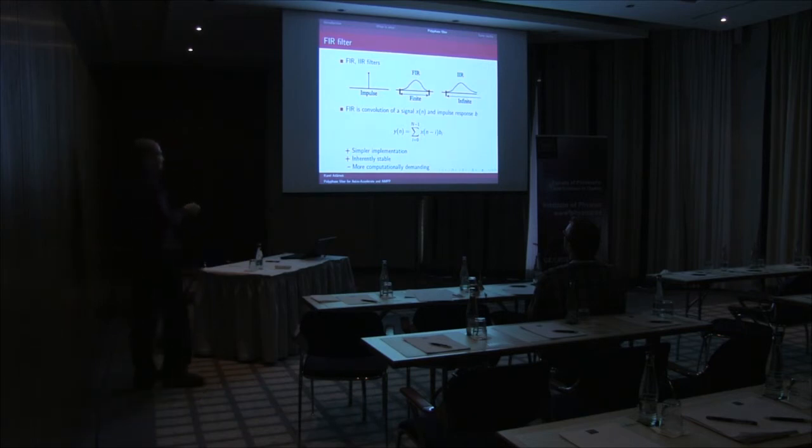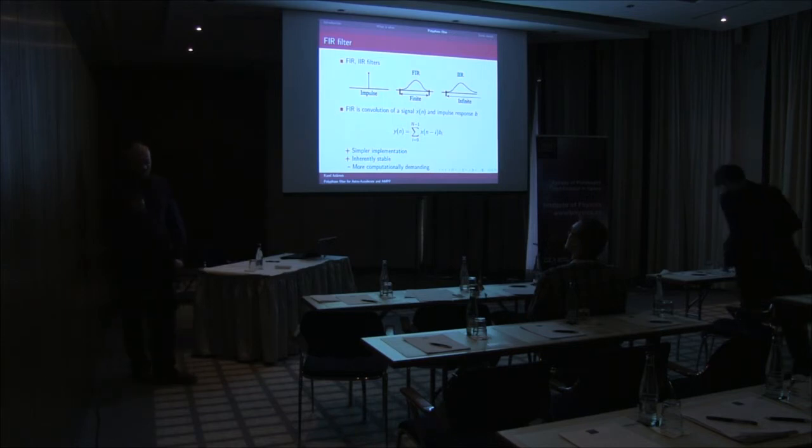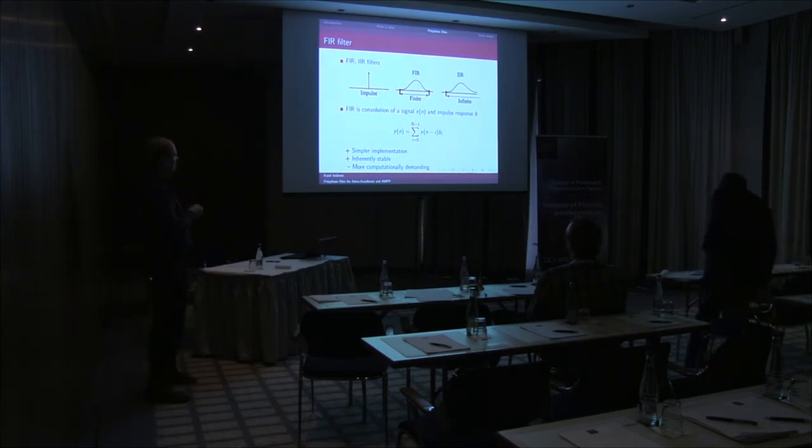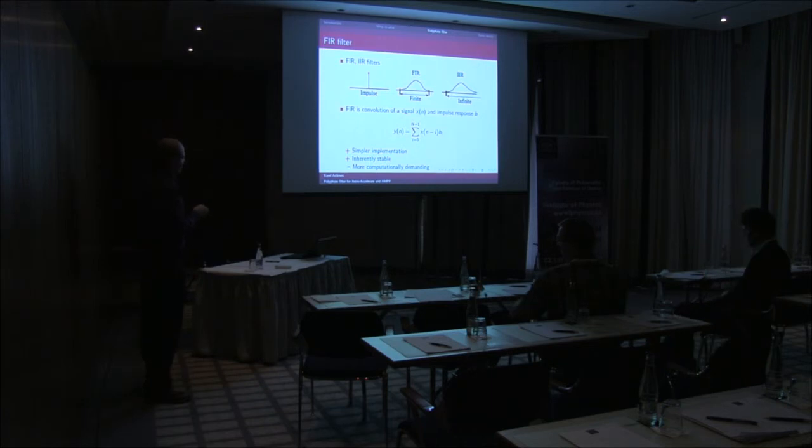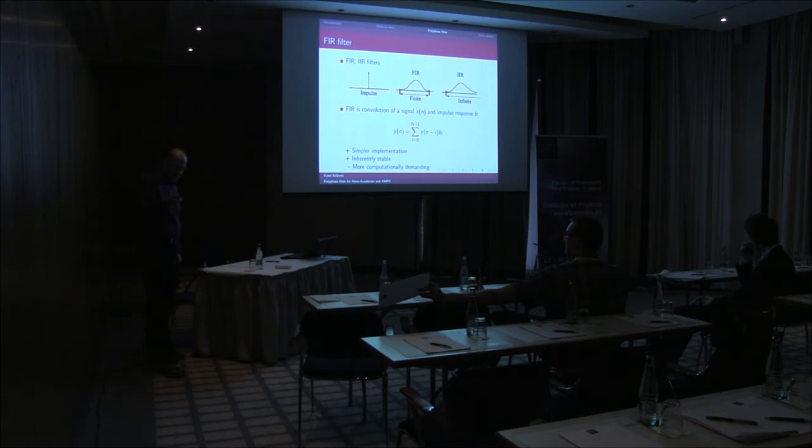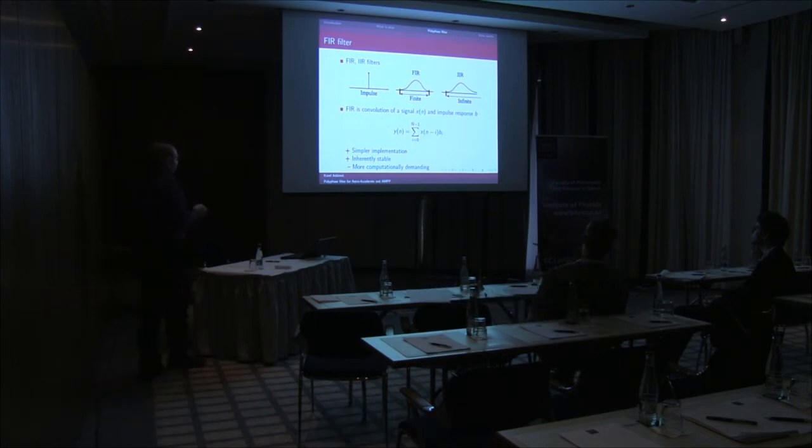And here you can see the main advantage, in my opinion, of the FIR filter. This is that the response of a FIR filter is finite in time. So if you get some kind of massive error in your real-time data, you will have some bad data in the end, but it will not spoil all of your data. So, the mathematical prescription for FIR filters is here.